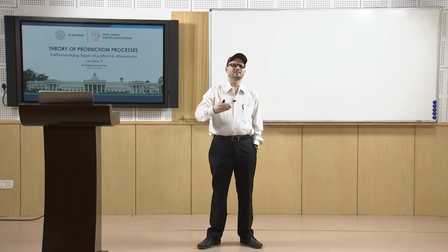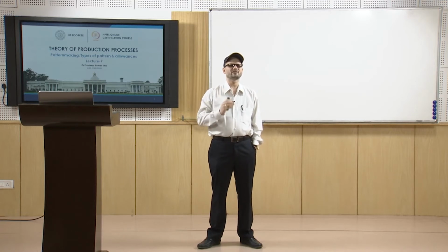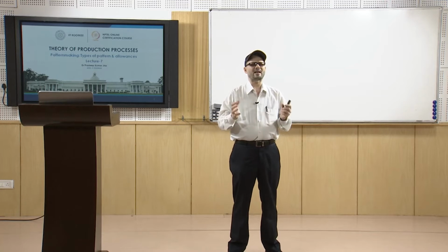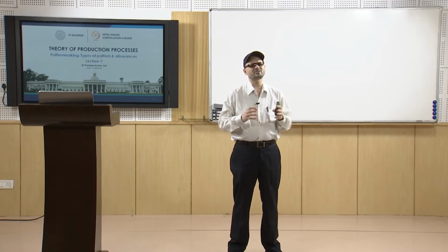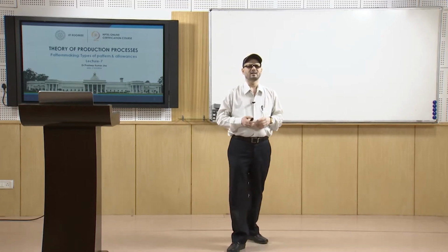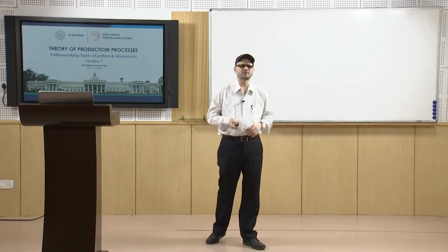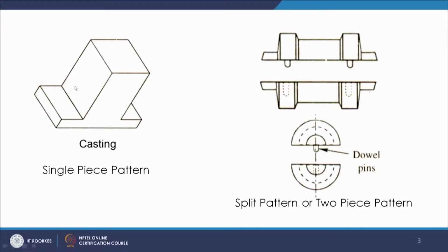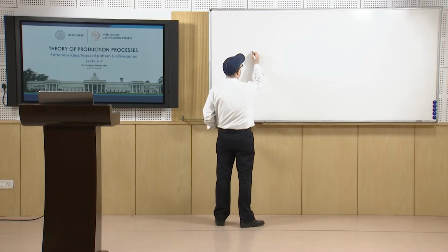Otherwise, you have design aspects to be considered, because ultimately the problem is how to withdraw the pattern once you are ramming the sand around it. If it is a simple shape pattern, like this single piece pattern, for this type of shape you can put the whole of the pattern in the drag, and you can ram the sand around it.